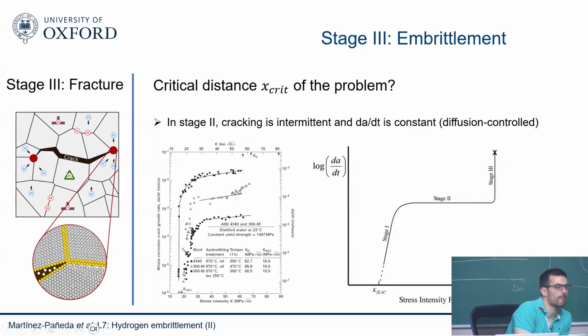So, because this cracking phenomenon is a stable crack growth occurring in an intermittent way, when we are carrying out tests in monotonic loading, do we get sufficient time for hydrogen to come, form this, and then the crack to grow? It depends on your loading rate, of course.